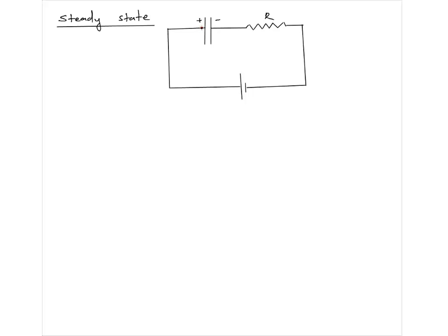Capacitor does not build charge instantly. It's not like you switch on the battery and the capacitor is fully charged. Not like that. As and when the capacitor gains more and more charge, it opposes the battery more and more. Positive terminal and positive terminal are not going to make good friends. Two batteries support each other if plus of one faces minus of the other. So even when the charge is building on the capacitor gradually, it is opposing the battery, right?